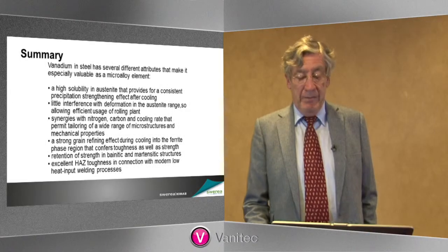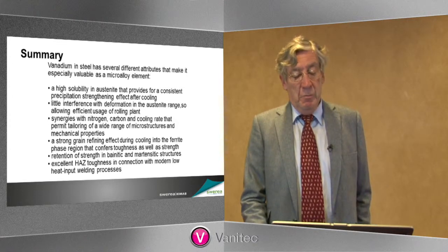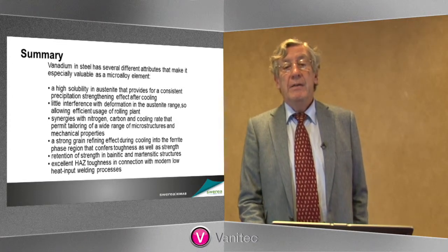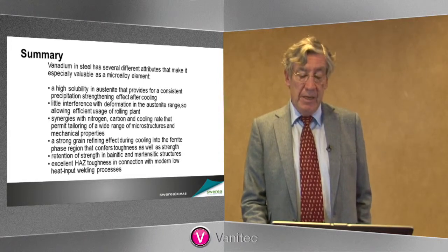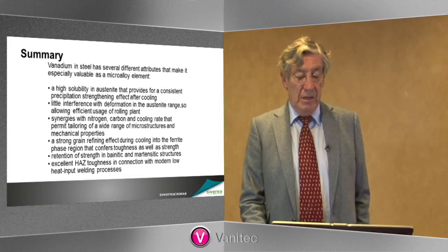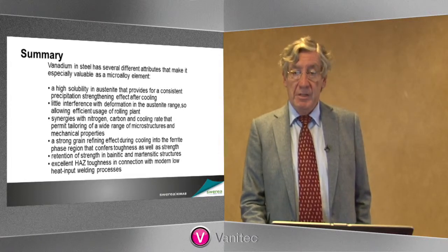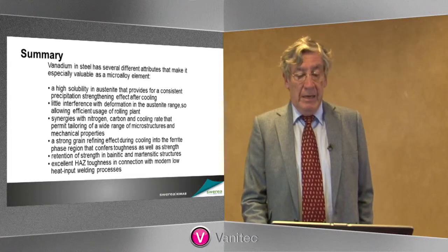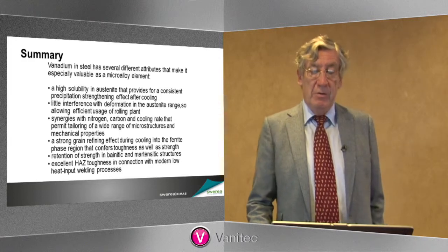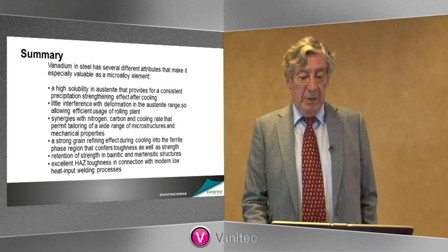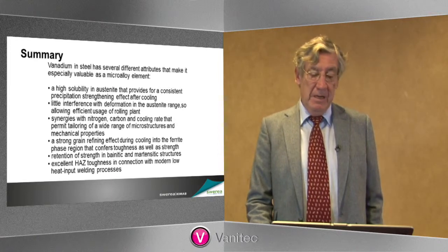And finally, though I haven't mentioned it at all, we are investigating and have discovered the heat-affected zone toughness in vanadium steels is extremely good under the conditions of welding that are used in the modern low-heat input processes. So this is an attempt to show you how vanadium can be considered as a versatile element. It does many different jobs in the steel.